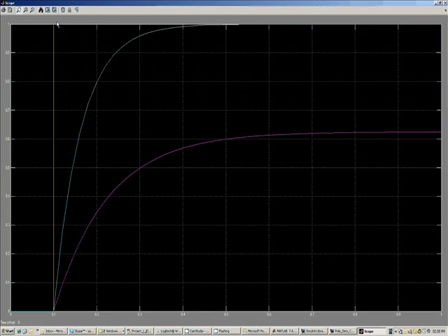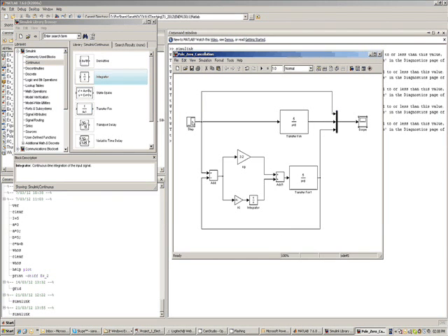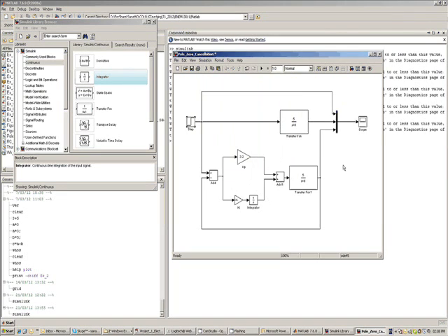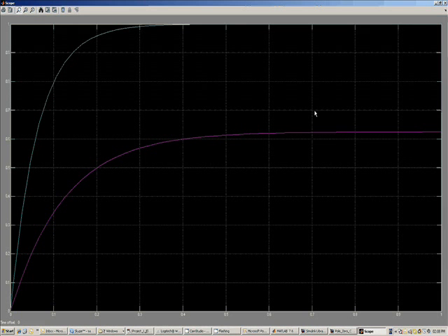Yeah. So now you can see that this is your input step, this is your open loop system output, and if you work out roughly 63% of 0.6, it will be 0.36 something, so somewhere here. Now since everything is working, let me just do one thing. I'll close this one and I'll reset the step so that we are applying the step at t equal to 0, which makes it easier for me to calculate all the times, time constants, etc.